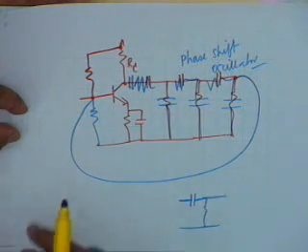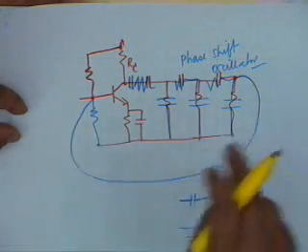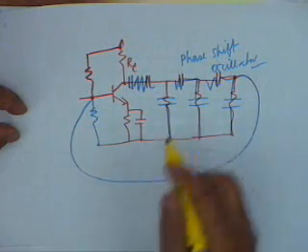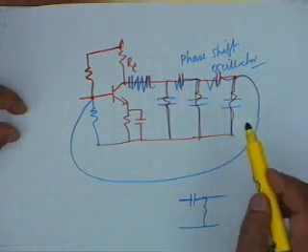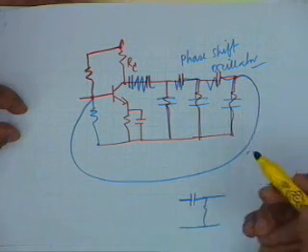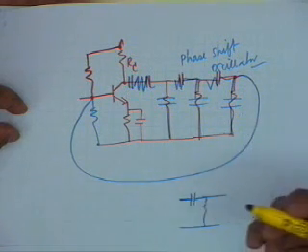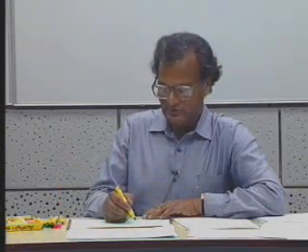On the other hand, if it is an RC circuit, the output shall lag the input, and therefore if we take RC, RC, RC, it shall be minus pi. Agreed. Plus pi or minus pi, it doesn't matter, either way it shall work. But the problem is how to analyze this circuit. What is the frequency of oscillation? Because the amplifier is not ideal. So what we do is like this.